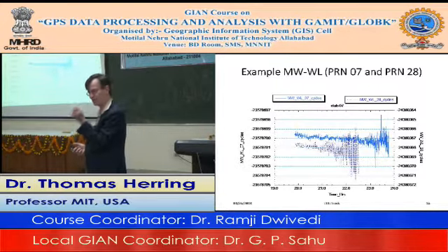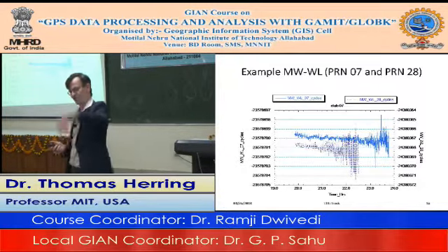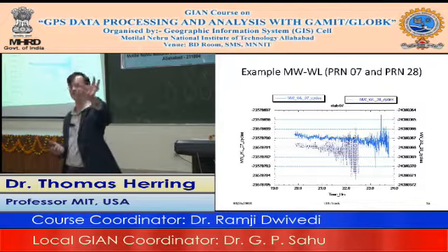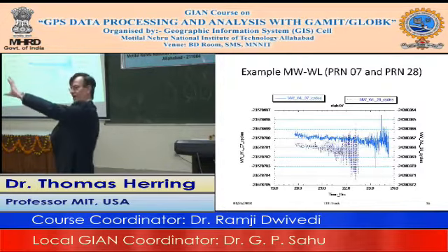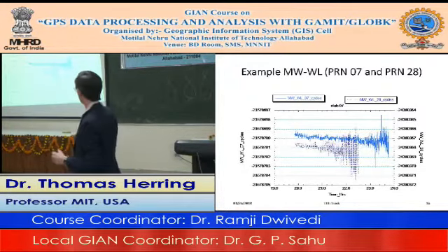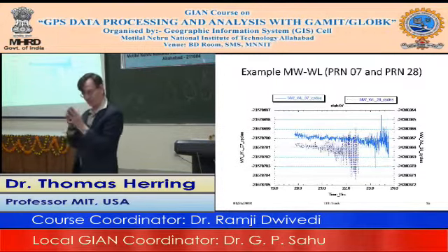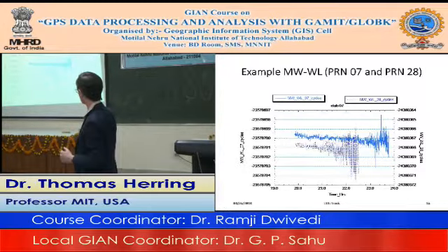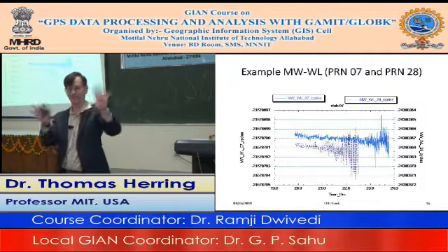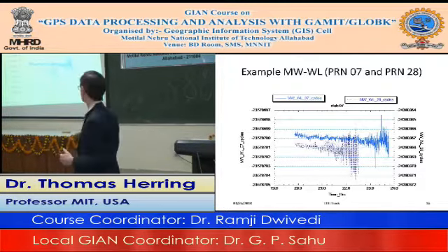And that is actually part of the problem with kinematic positioning, is when the satellites are getting low on the horizon, the noise in everything is increasing dramatically. And also, when it's low on the horizon is the time when you're likely to hit an obstruction. If you're driving along, you're likely to go by a building, and the building will block the sky. And then when it reappears on the other side of the building, the only thing you have left is this really noisy data. So that's what track is doing, it's looking at that stuff, and some of these little noisy segments of data, it's just going to say, that was just far too short after I reappeared after the building, and I won't be able to use it, and it will throw it away. That's part of the logic. Or it might keep it, but it won't be able to resolve it to an integer ambiguity successfully.